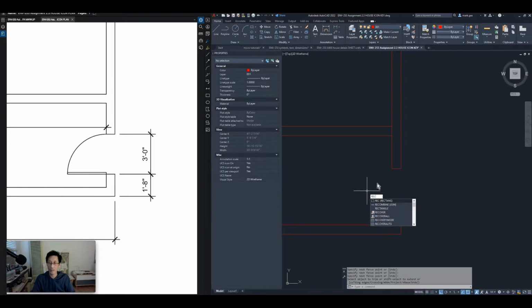And I'll just do a rectangle, and I can draw it anywhere in space, and then I'll move it first. So again, we'll just click anywhere. I'll start moving my mouse. And again, the width of the door itself is 36 inches. So I'll do 36 in that direction, comma, and I said the thickness of the door is 1.5 inches. So comma 1.5, enter.